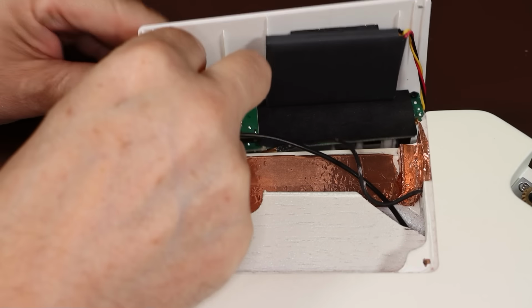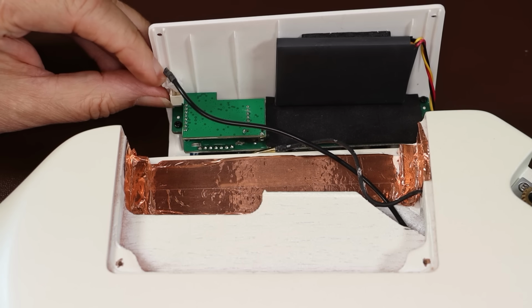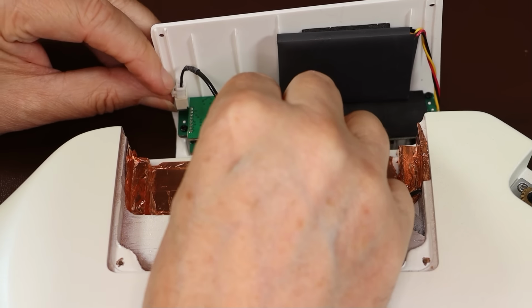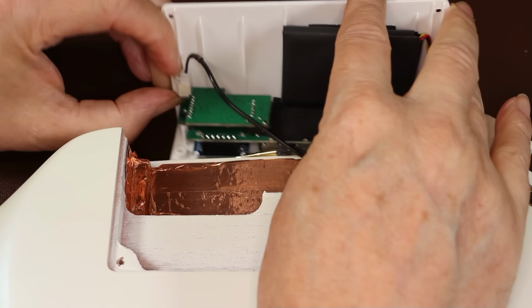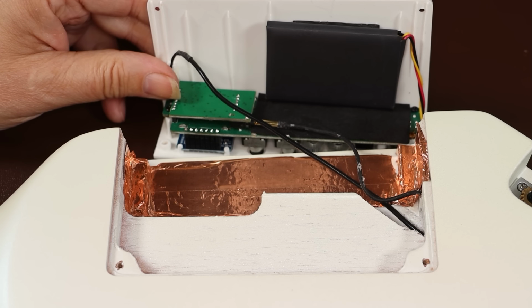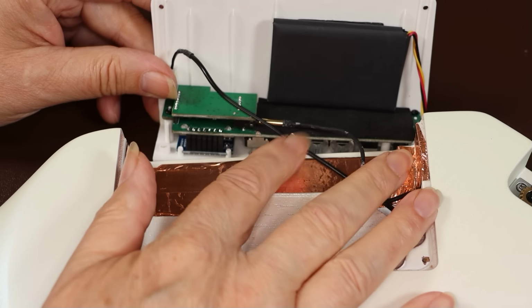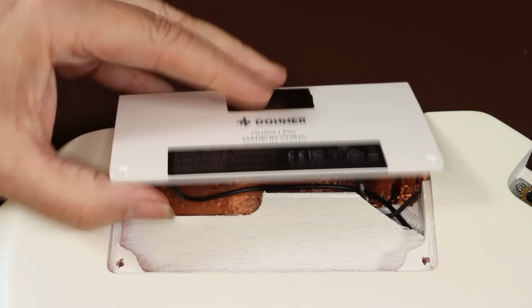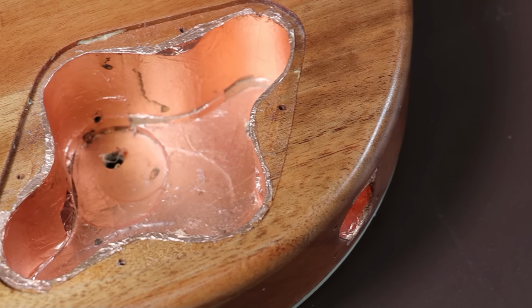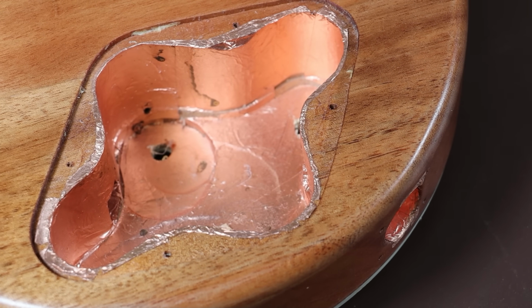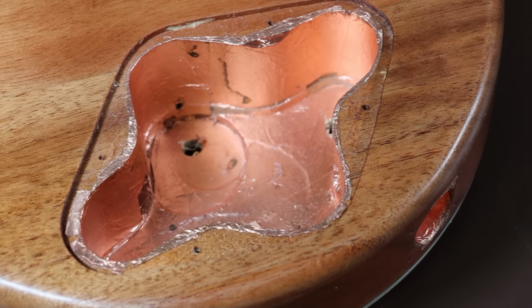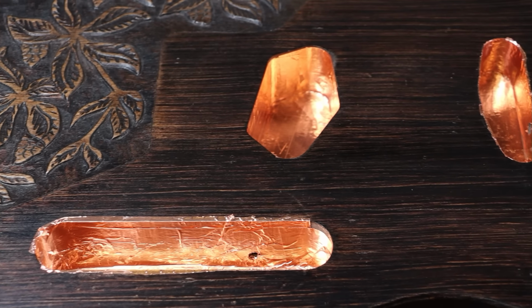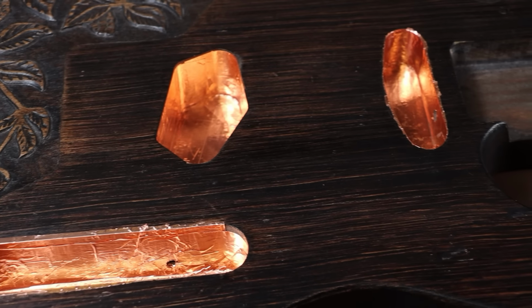If you ever rewire a guitar or build a guitar or do any big repairs like changing pickups, it's always worthwhile checking the screening whilst you're there and maybe upgrading it. Whenever I build a guitar, I always line every cavity with screening, and you can see my preferred material is copper. And I don't know of any advantages or disadvantages of using copper, but I always get good results from it.